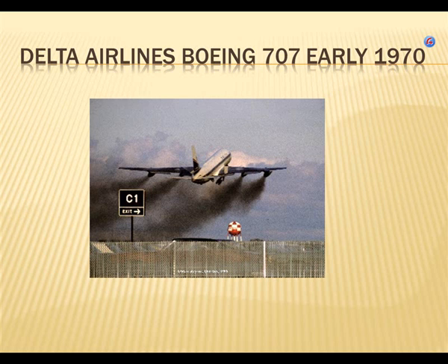So since then, what they've done is not necessarily clean up the fuel, but now they use less of it because the jet engine drives a fan. And the fan brings in pure air along the side of the engine and exhausts. The fan drives the air around the engine and out the back. They initially called them fan jets. It's because a high percentage of the thrust comes not from the jet engine, but from the air being driven alongside the jet engine.